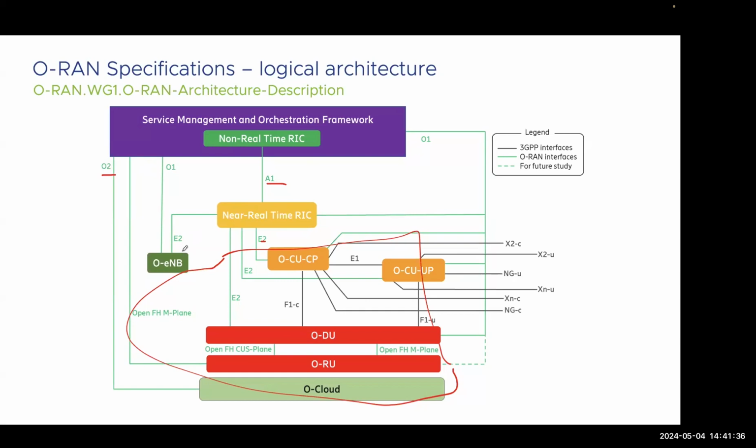It's more complex because of the massive MIMO and all the related. You will use a grid of beams. How you frame massive MIMO and the beamforming is a session we can talk about for 2 hours, but there are many technologies using CSI-RS, and how you do the beamforming is complex.